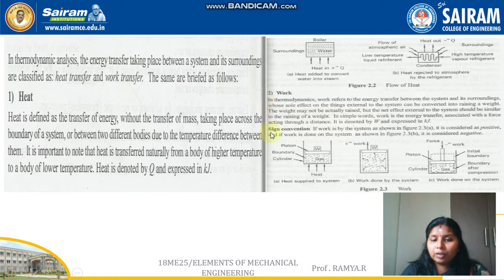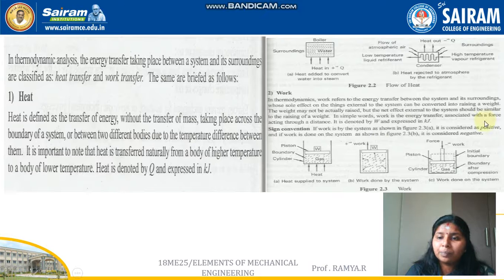And the next one, work. In thermodynamics, work refers to energy transfer between the system and its surroundings, whose sole effect on things external to the system can be converted into raising a weight. The weight may not actually be raised, but the net effect external to the system should be similar to the raising of a weight. In simple words, work is a transfer of energy associated with a force acting through a distance. It is denoted as W and expressed in kilojoules.